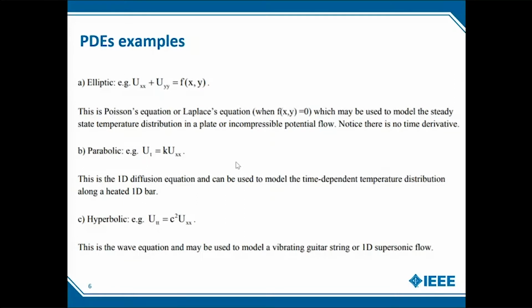But on the other hand, in space, we can go either x equal to 0 to minus L or x equal to 0 to L. So we can go in both the directions. But when it comes to time, it's always in the forward direction. And that is why these type of equations are known as forward marching. And always remember that the parabolic equation will have a derivative with respect to time. An example of this one is basically if you consider 1D diffusion of heat in a bar, and basically transient diffusion or a steady state diffusion.